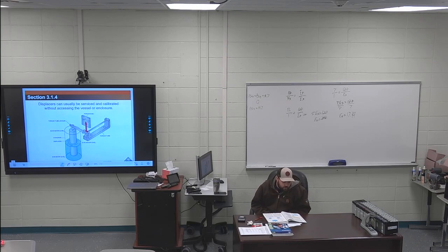So 320 indirect level measurement, 321, the whole bottom left is highlighted. So first like 3 sentences. Measuring the levels of caustic liquids and acids poses special challenges. Using a measuring system that is equipped with components made of highly corrosive resistant materials that cost too much to be practical. Using an indirect method of level measurement, such as a magnetic float system, is one way to overcome this challenge.